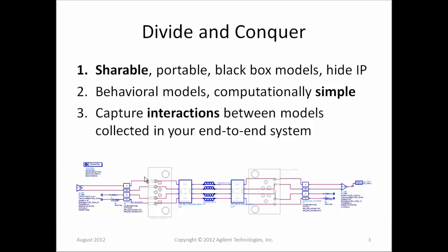This is a very important point that is very deceptive, in the sense that you're thinking about a signal going from this transmitter left to right, kind of unidirectionally towards the receiver, but in fact nature doesn't care about your goal of being a unilateral system. This is actually a bilateral system. You get reflections off of all these components, and there are signals actually moving from left to right and from right to left, and you have to take these into account because they affect the end result.